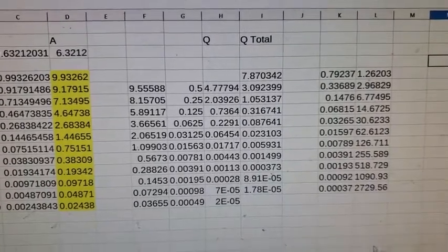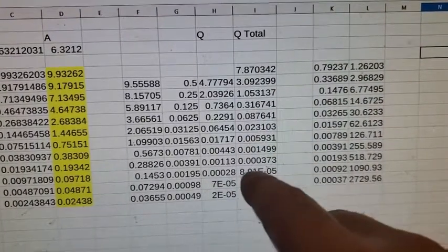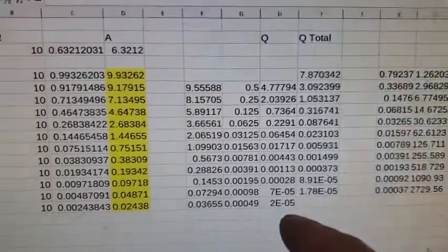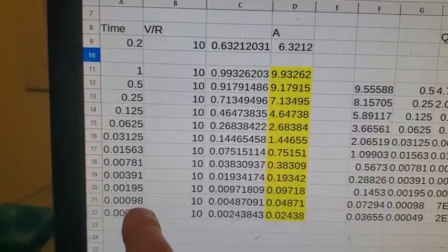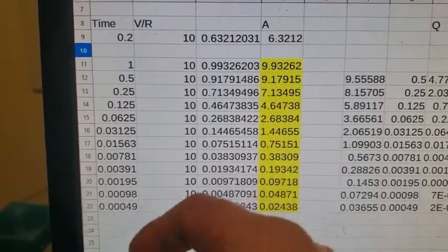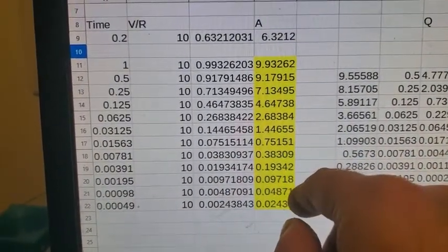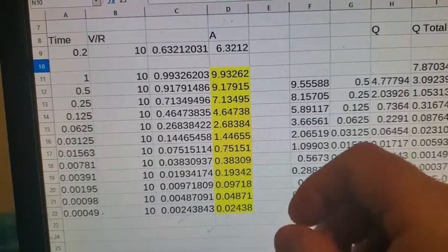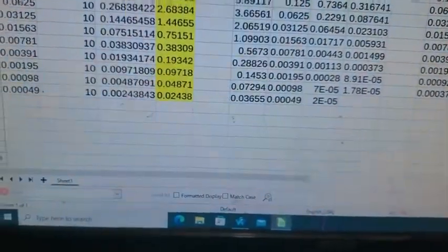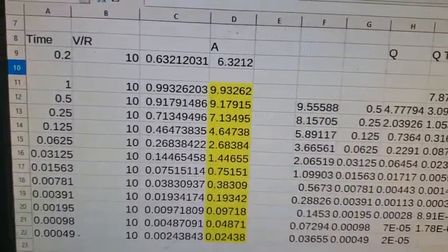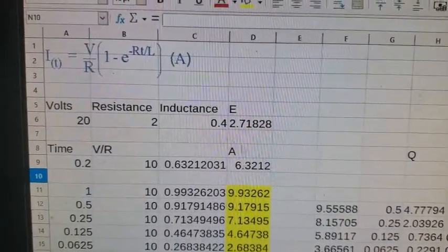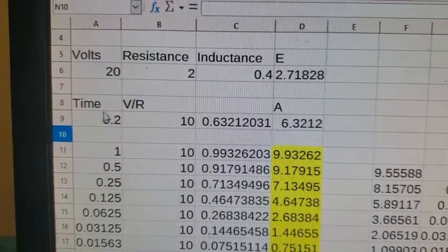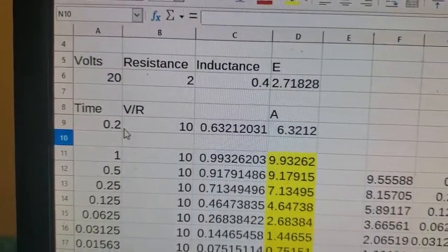And one of the things is that with an LC circuit, the resonance is also affecting the spike. Furthermore, if you have a very brief pulse, will your diode even be able to catch it? Will it be able to rectify it? Further, if it's very weak, then perhaps you run into other issues with components. So one thing you might think to do is, if you have a very low resistance, high inductance coil, that's going to make your tau time, instead of 0.2, maybe like 2 seconds.